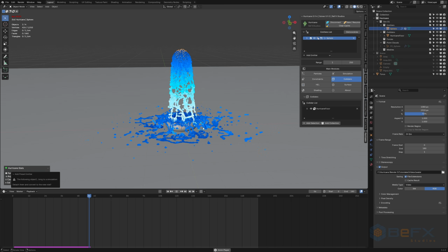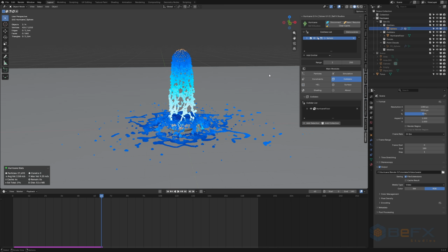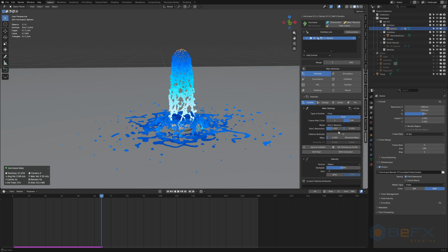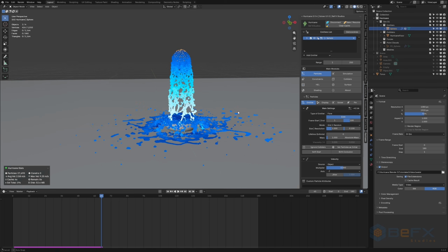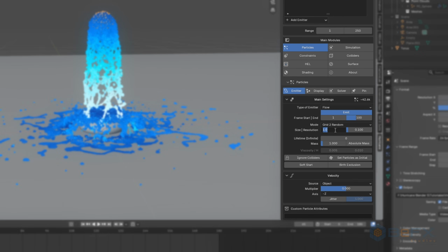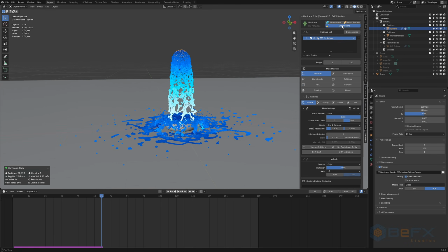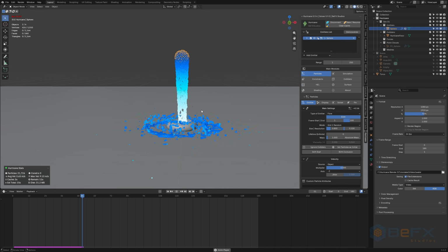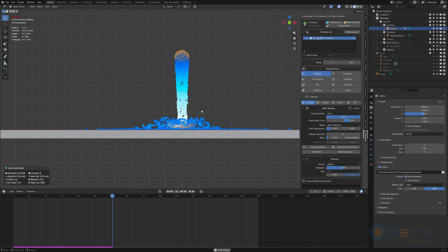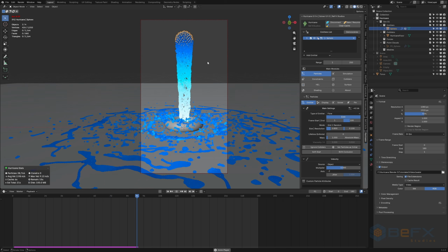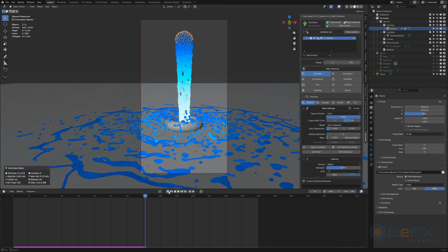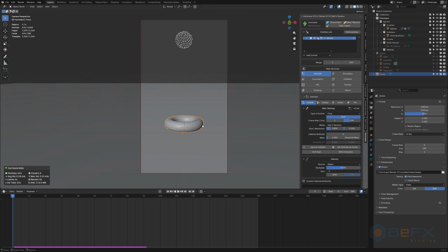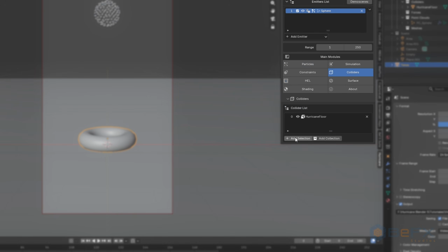as we will still need to tune a few key settings to adapt the behavior to the specific emitter type we've added. First, we slightly reduce the particle size. This helps them to concentrate better around the emission point without over-dispersing. With just this adjustment, we achieve a much more consistent fluid stream. Next, we add the torus as a collider and slightly tweak the floor's friction value.